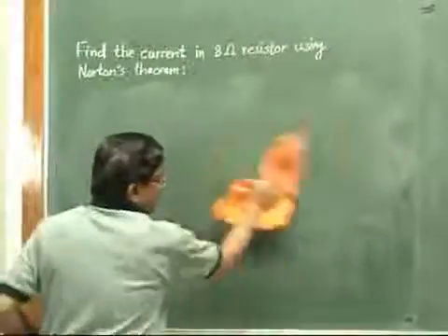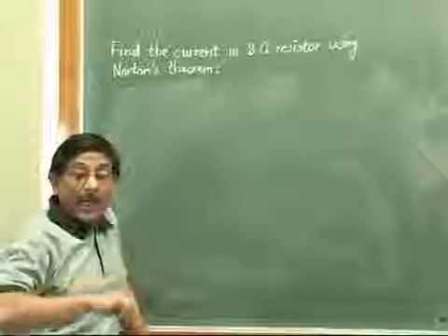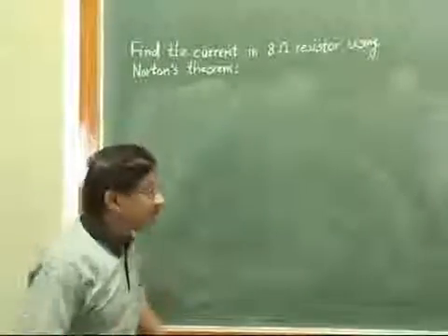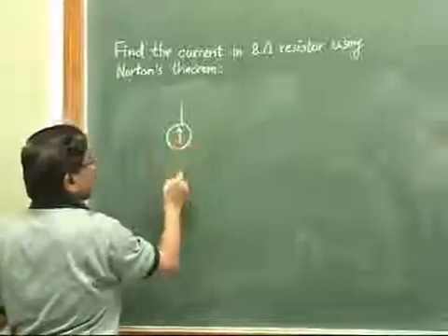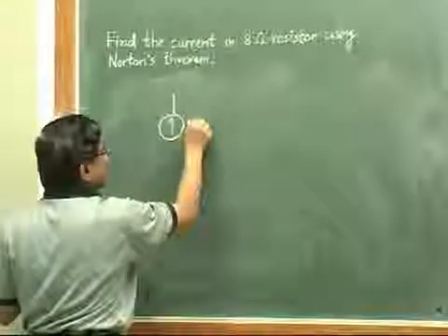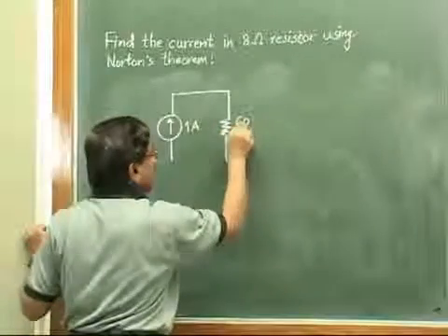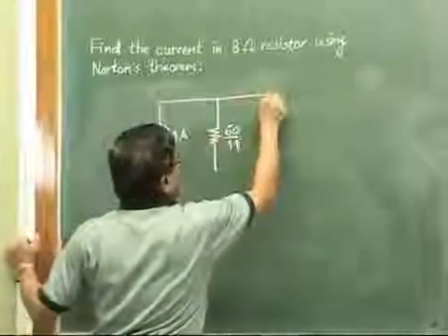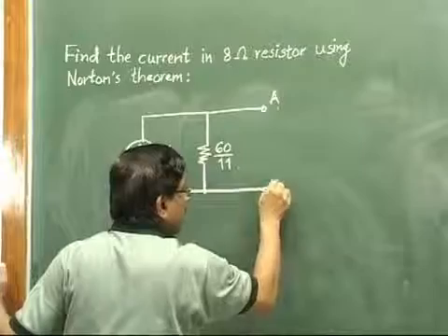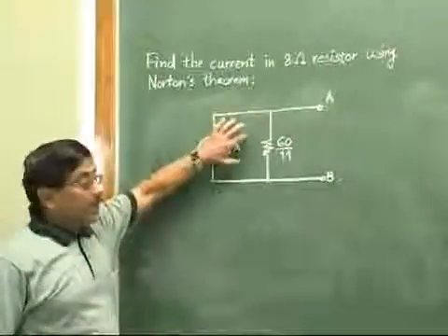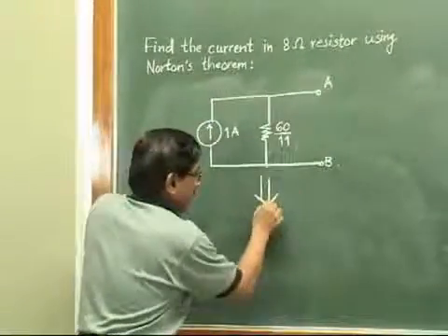Just let us switch to our previous knowledge of the conversion of practical current or voltage sources. For example, if I have this circuit as the given circuit like this, and this value is given as say 1 ampere, then this current source is, suppose, parallel to a resistor of 60/11 ohm. And suppose these are some open terminals, A and B. And suppose my question is, convert this given practical current source into an equivalent voltage source. Then what would be the things?